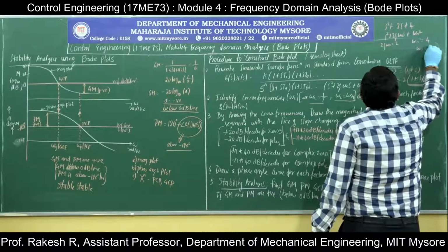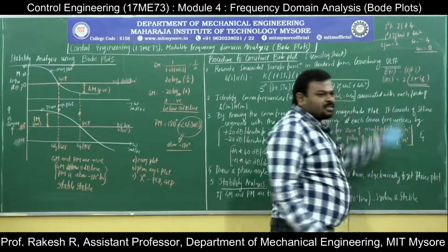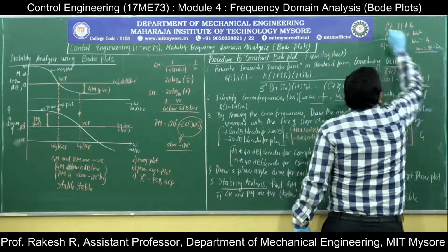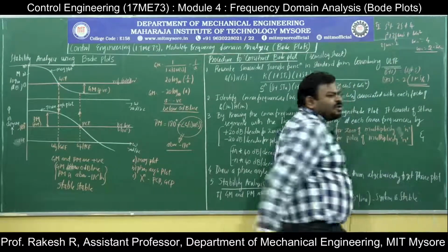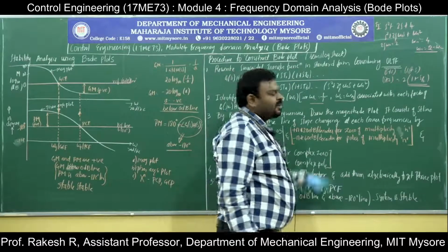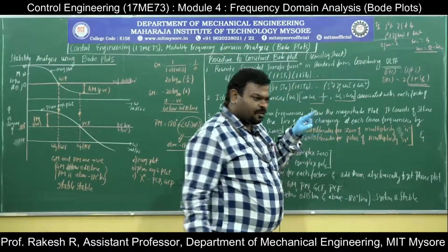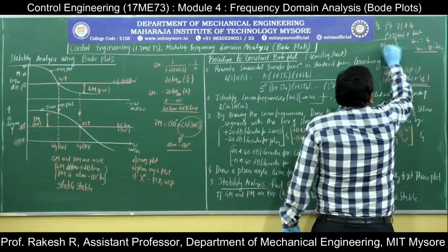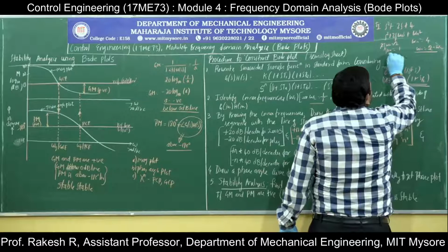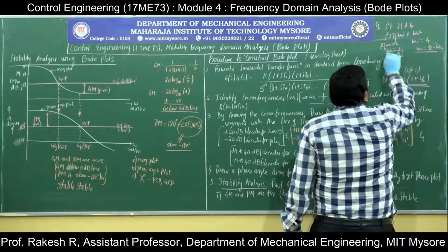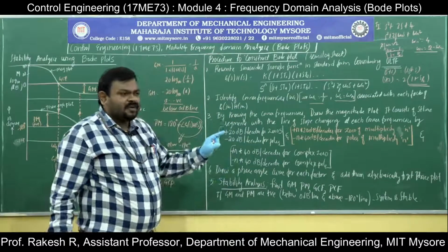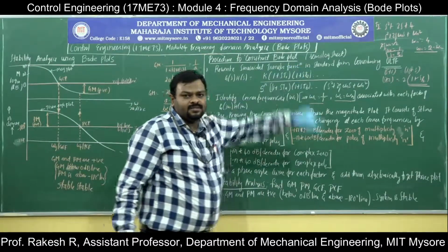4. Omega n is equal to 2. So this omega n is equal to 2. It is just an example. This itself is omega c here. And what is the value of zeta? Why do we want zeta there? In the phase angle we need zeta: 2 zeta omega by omega n divided by 1 minus omega by omega n whole square. So zeta omega n is equal to 1, so zeta is equal to 1 by 2. So this is how you need to calculate the zeta and omega n for a second order system, s square terms.